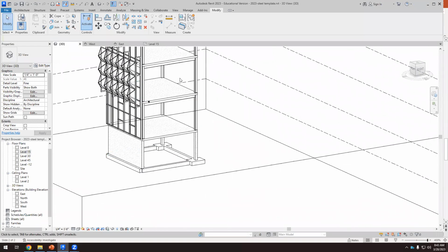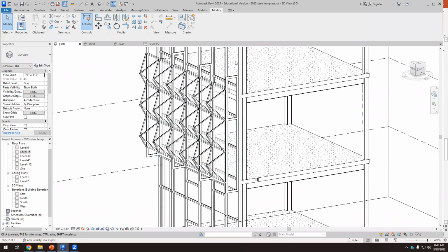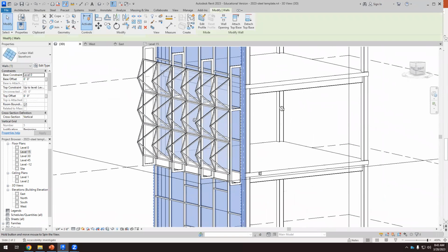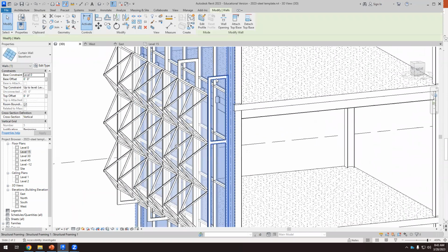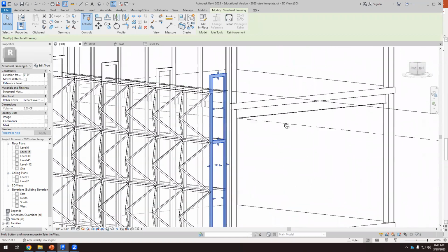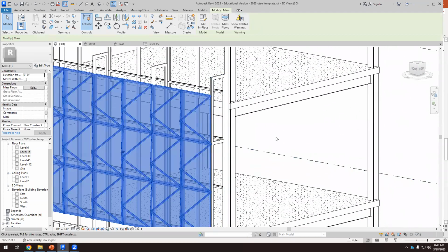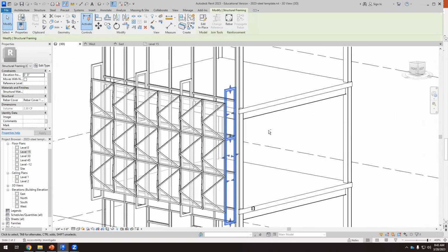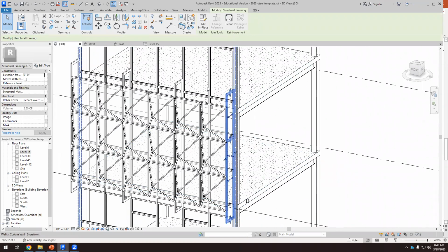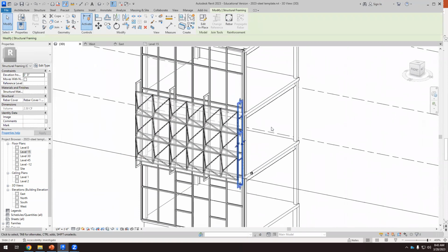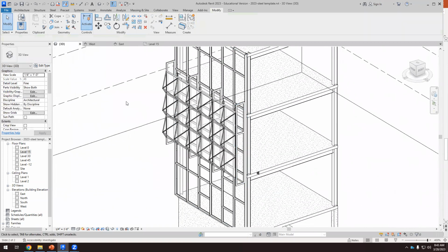So let's continue. We have the first curtain wall. We have that structure connecting both layers, and this is the second curtain wall. So that structure, we might need it in every single vertical mullion, or maybe we don't need it, but the fewer elements, the better, the cheaper it will be, but it comes from calculations.